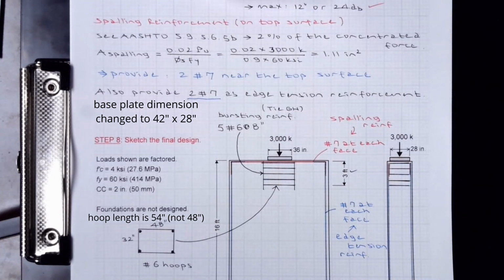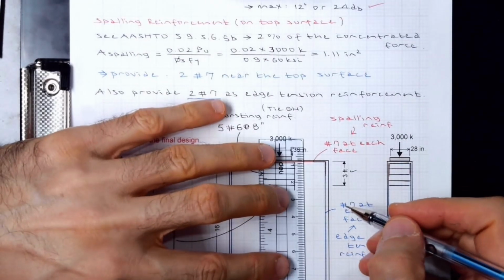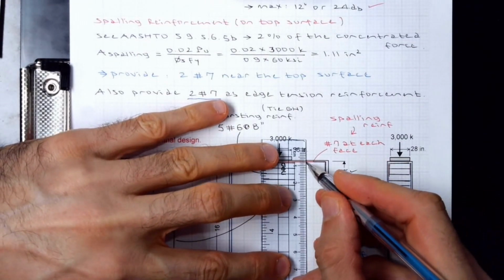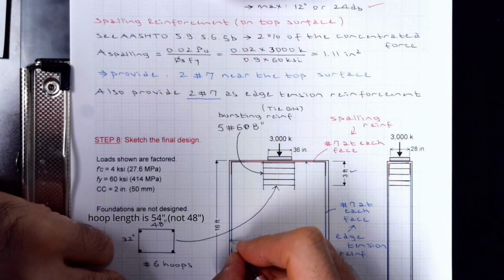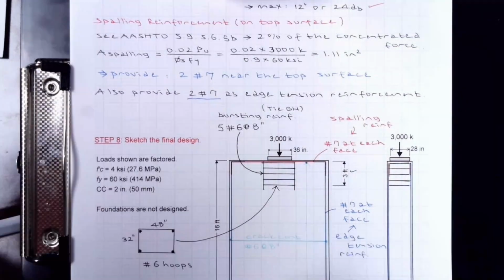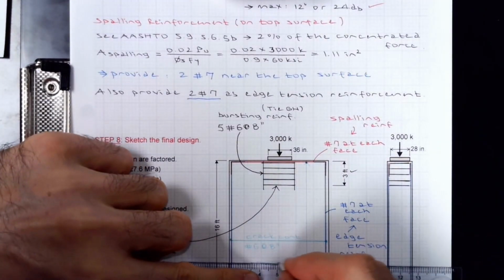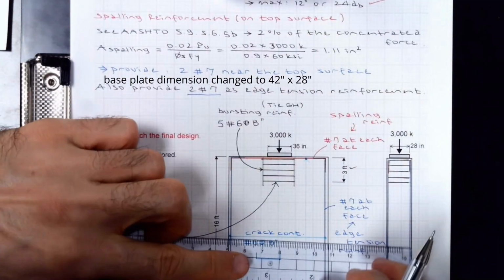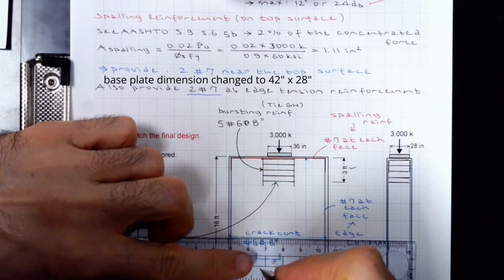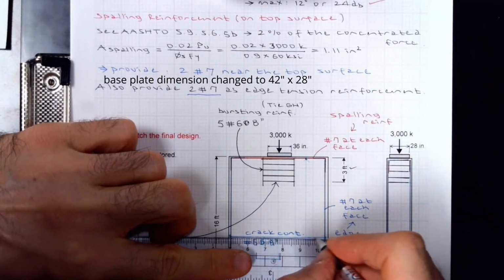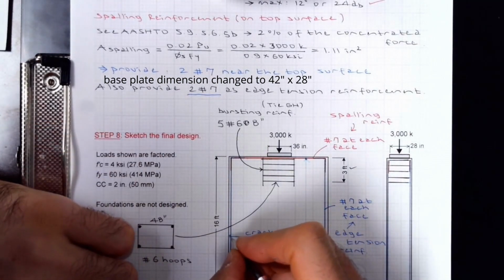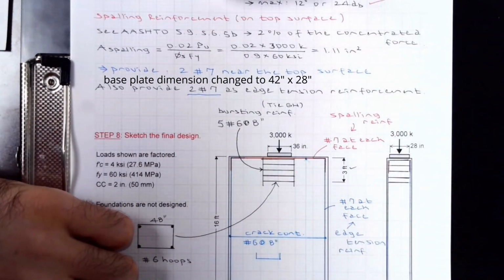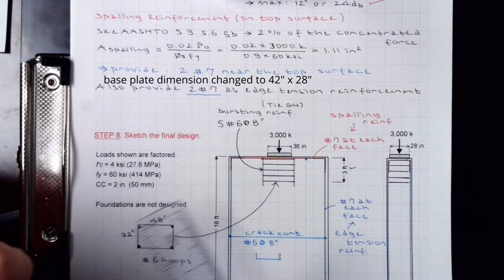The final addition would be crack control reinforcement, which is going to act as if it was the main reinforcement because it governed it. It's going to be covering the entire section. You want to hook this inside, so I'm just showing you those hooks, and also it's a good idea to show it here. Crack control reinforcement, it's going to be extending from one side to other one, hooked inside. So I'm just showing 2 dots to indicate it goes inside through the thickness.